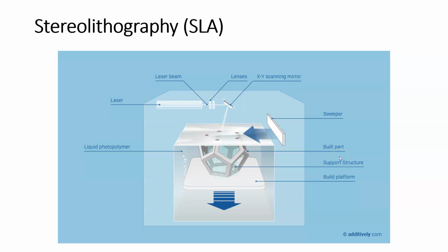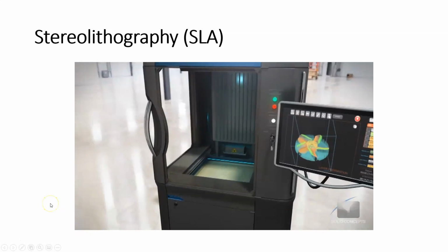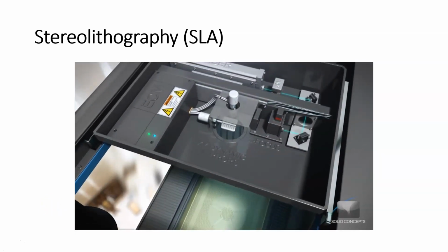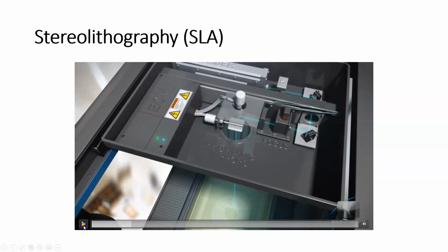All right. Now, we'll watch a video here of the stereolithography process. There's no sound in this, so I'll talk over it. Here you can see the laser. Let me just stop it right here. So you can see the laser up here, and it's shooting through some focusing lens and some mirrors to direct it into the right location. And then this mirror right here is the galvanometer. You can see it's attached to a servo. This might also be, it's hard for me to see, but this might also be a galvanometer. So it's going to be directing off that, and you can see it's going to be moving downward into the vat. All right, so let's continue this.